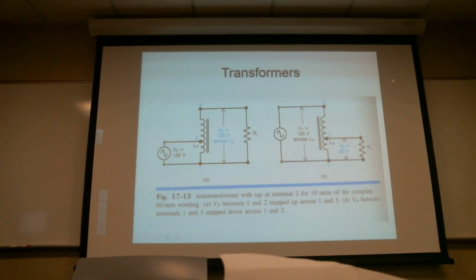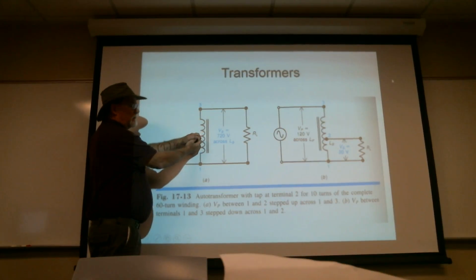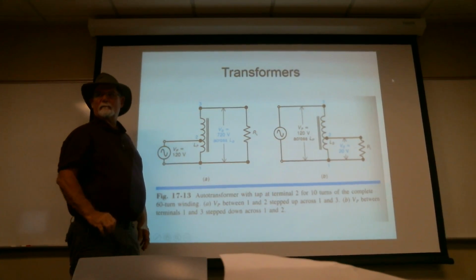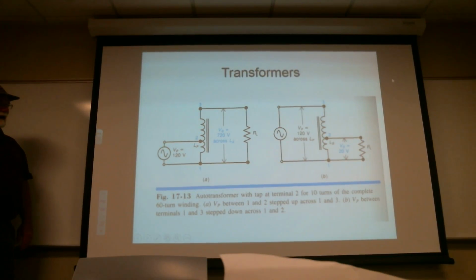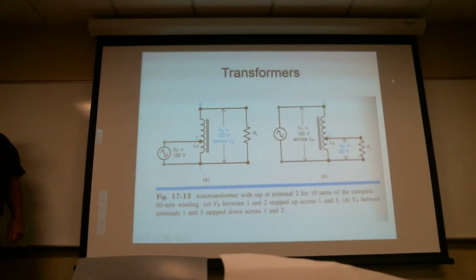So yeah, here we're starting to get into the multi-tap, where essentially all of this is bundled together, so all the magnetism is felt across everything. That's where it gets a little confusing theoretically, but manufacturing wise it's really easy to make. I just take and make one big coil, and somewhere in the middle I can have another lead coming out, right?